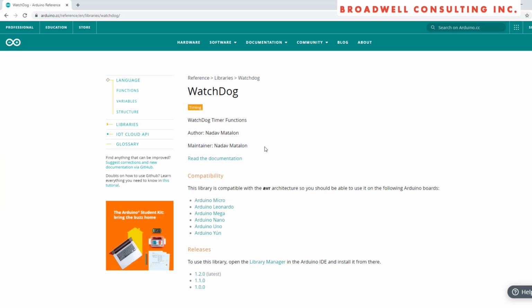We know that the Arduino also has some Watchdog libraries available that can cause internal resets. Like a lot of the Arduino functions, each library is only compatible with certain Arduinos because the Watchdog tends to be hardware dependent. In the case of the Arduino Uno, the most popular Watchdog has a maximum expiration time of 4 seconds. So one reason you might want to use the Serial Wombat is that it has a period that can reach all the way up to 65,000 milliseconds or 65 seconds, a little over a minute.